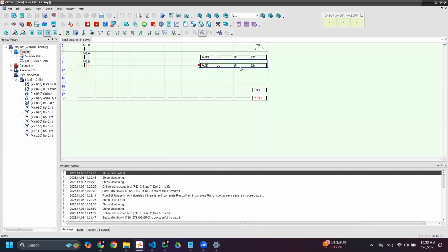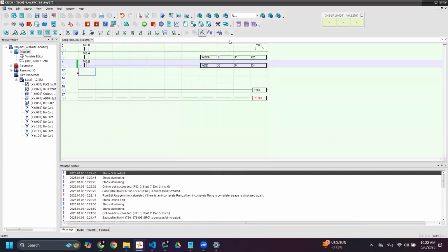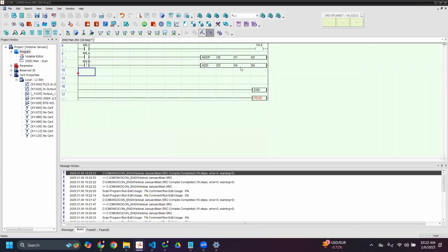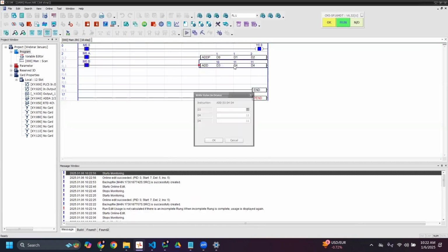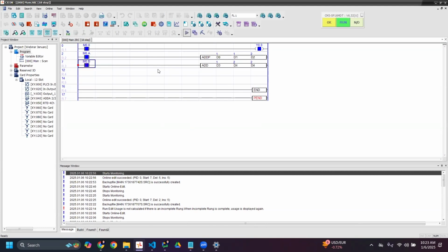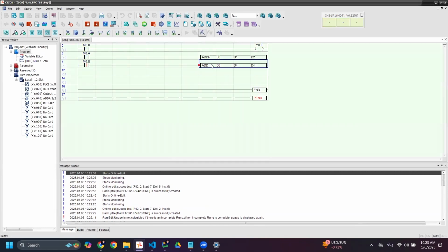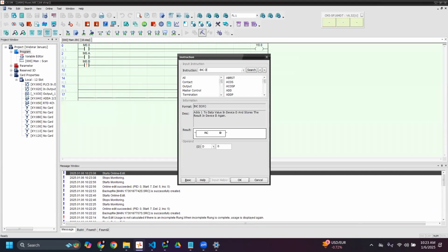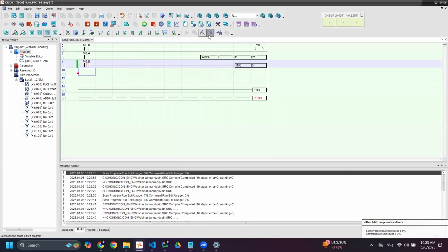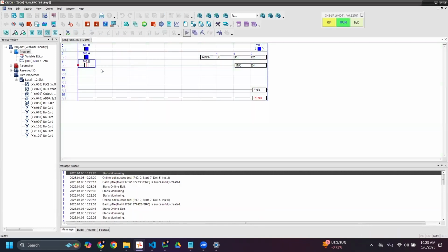You can also use the same data registers over. So if I wanted to do this, I'd do D3 plus D4 and save that into D4. I can do 1 and 1, and this should be a simple incrementing counter. And we do offer other instructions as well that can actually do what I was just doing with increasing. So I can do D-inc D4, and this will accomplish the same effect.